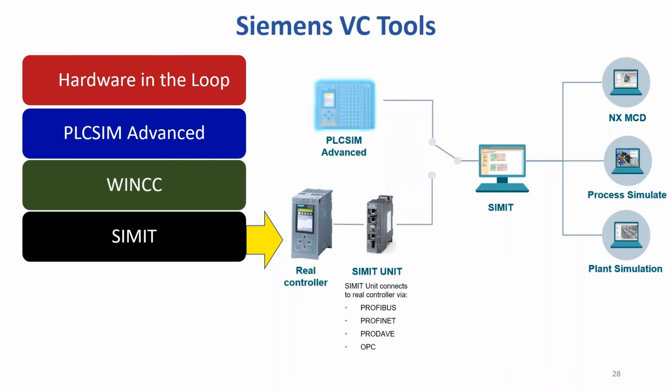SIMIT is a simulation platform that is capable of comprehensive automation, project testing, and process commissioning, all in one platform. It can also be used as a training tool to teach operators and maintenance how to efficiently run their plant. SIMIT can communicate with hardware, PLCSIM Advanced, and NX MCD, Process Simulate, and Plant Simulation. Note, SIMIT lets you easily switch between software-in-the-loop commissioning using PLCSIM Advanced and hardware-in-the-loop using SIMIT units, all in one place.